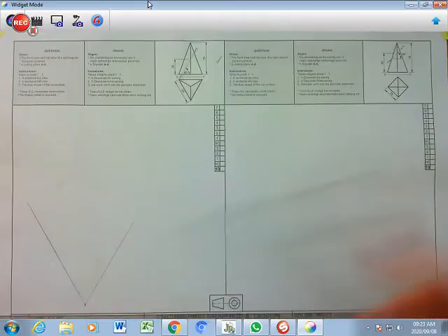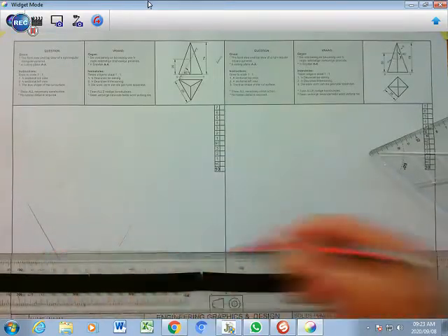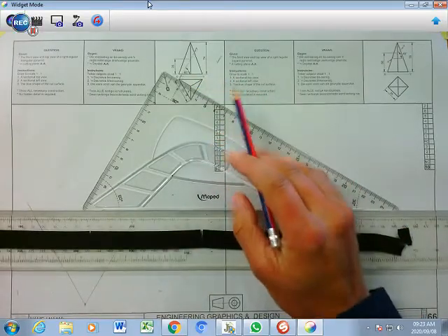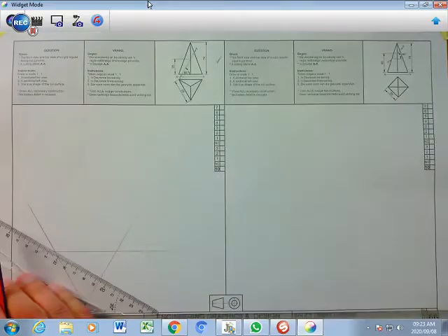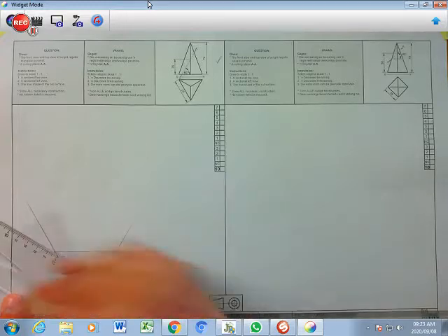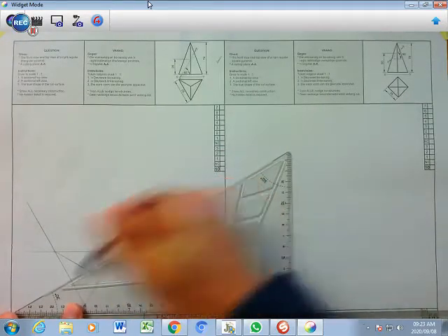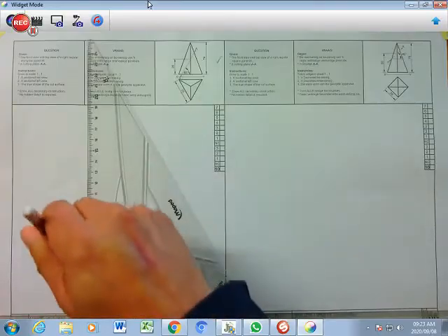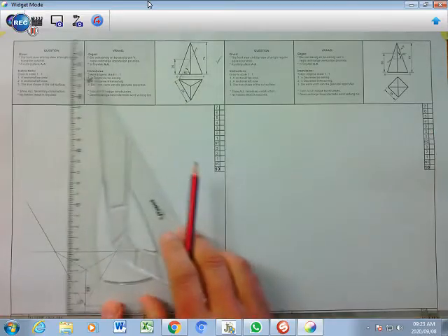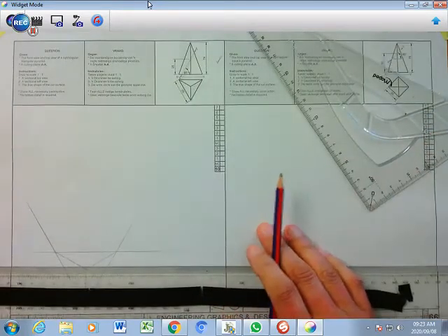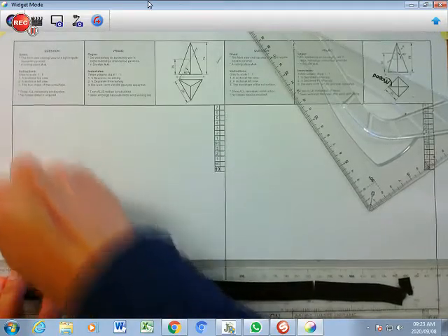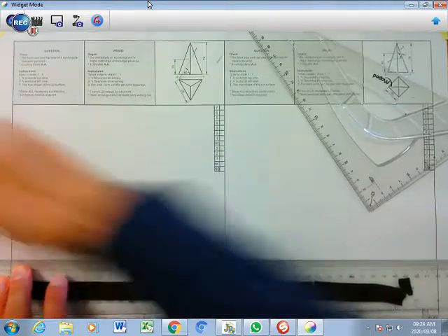There's my 55. I'm going to project that across there, and then if I want to see what angle these lines inside the triangle are, it's 30 degrees, so I'm going to draw that 30 degrees there, just a little bit darker from each corner, and then straight down that way. I'm going to leave that faint as it is. I'm going to project up, so any distance up. Before I do that, I just want to erase those lengthy construction lines there.